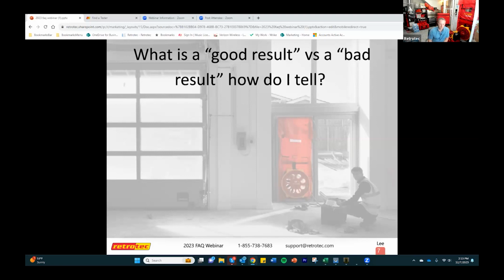General recommendations here are make sure that your envelope or your duct is set up as it should be. So if you're doing a duct test, make sure all your registers are sealed, and nothing's going to pop off while you're testing. If you're doing a blower door test, make sure all your windows and doors are shut, all the interior doors are open. Just have your preparation set and make sure that nothing's going to change while you're recording. And then for taking an actual point, you want to make sure you're using the smallest range that lets you get to your target pressure, a general recommendation that'll ensure you get a good result.